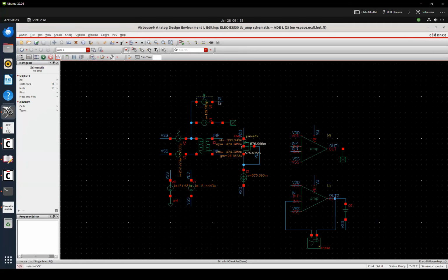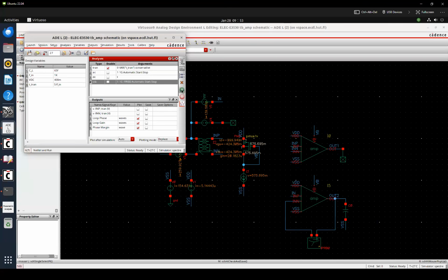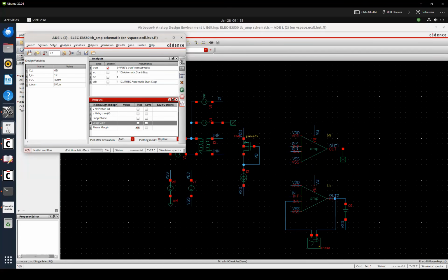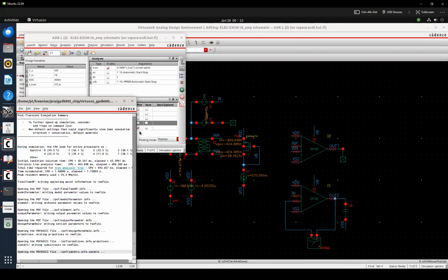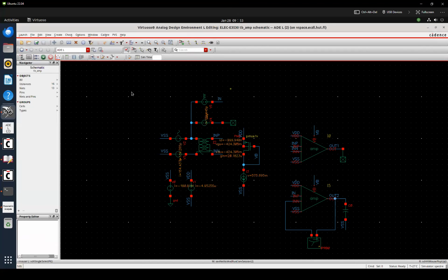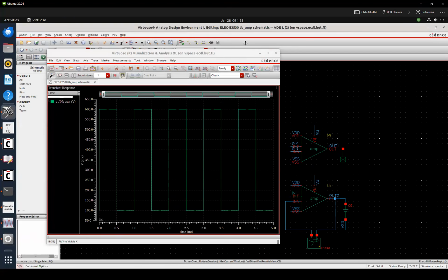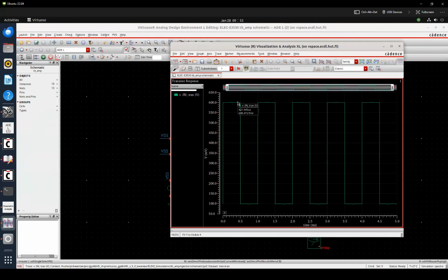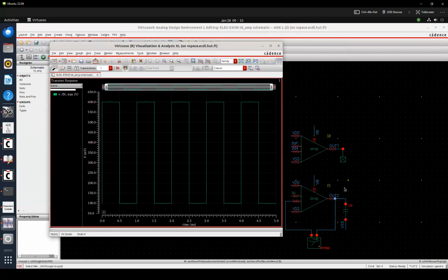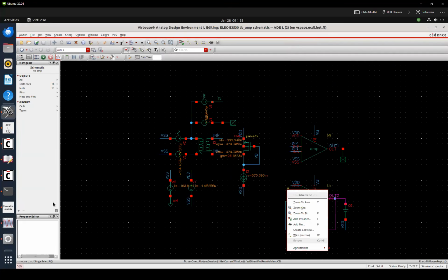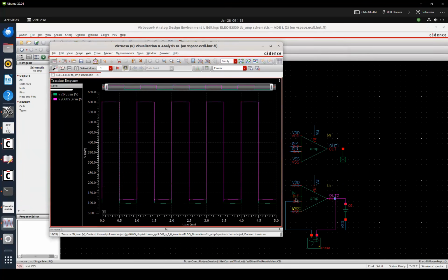And we have to make sure this input now changes to V pulse. If you run the simulation, okay, and we can plot the transient simulation, then we get this input voltage nicely changing from 0.1 volt to 0.6 volt. And if you plot the output node, you can see that the output node follows the input nicely, except for this one, right?